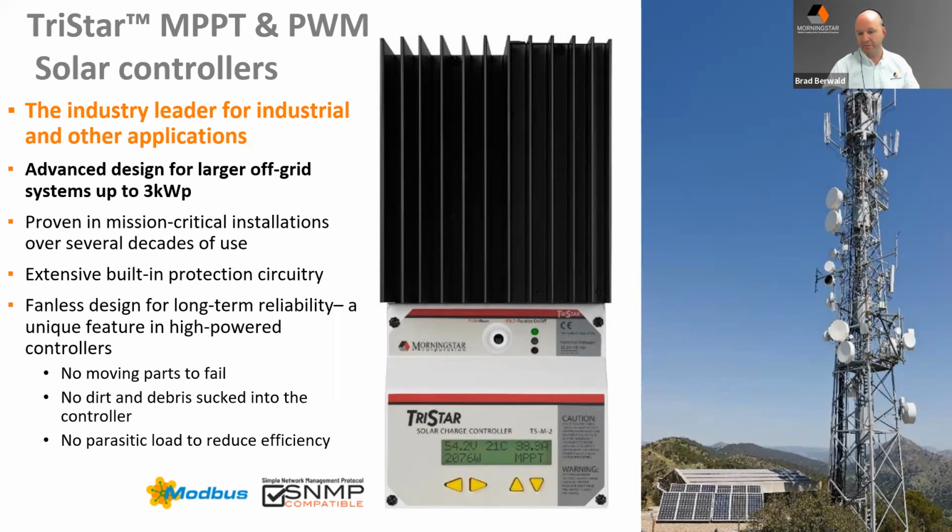used, sometimes many, for systems like on the right there, densely populated telecommunications towers that need a significant amount of solar array. So 3 kilowatts peak generally per controller. Oversizing of the array is a very common practice now, and something we addressed in our string sizer. So we see, just like with grid tie systems, even 4 kilowatts of PV put on a 3 kilowatt controller so that you get more consistent power output, through inclement weather or days when the insolation levels are not as